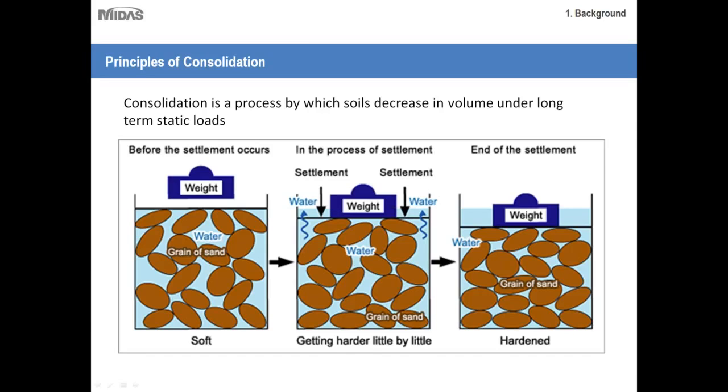If you're working in a very clay-filled area that's saturated, and you build any sort of structure upon it, you can expect a certain degree of consolidation. Now, this consolidation can take several weeks, or can also take several years, which we'll go into later, which tends to complicate design projects that are built in these areas. For projects built in very clay areas, this is something you really need to take into account, and you really need to study before you can commit to any final design.